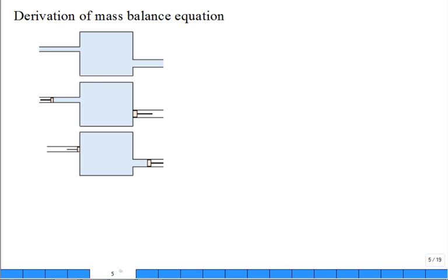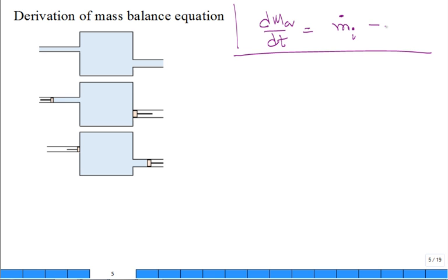We already know the conservation of mass equation. Do you know it so well that you could write it by heart? The rate of change of mass in the control volume with respect to time can go up if I have inflow, and can go down if I have outflow or exiting flow. And so if I just show it for one inlet pipe, one outlet pipe, that's a good equation for the conservation of mass. True? Let's pretend we didn't know that equation, and let's derive it using this little illustration here